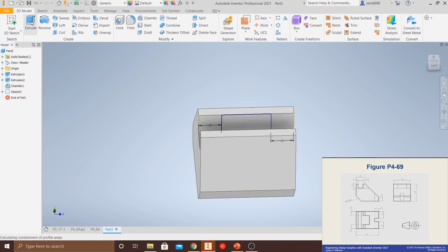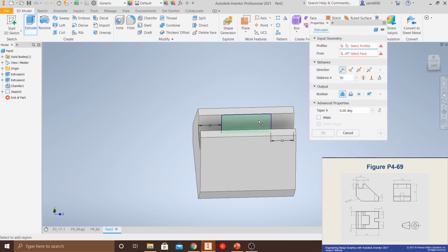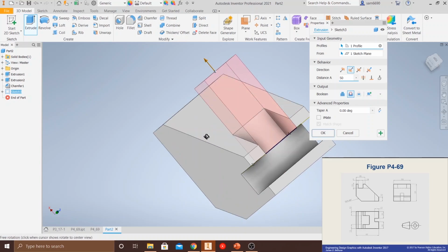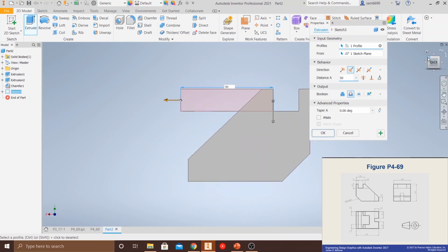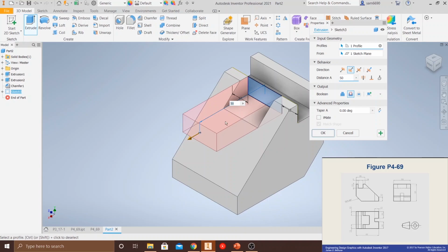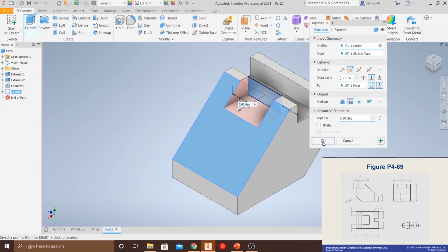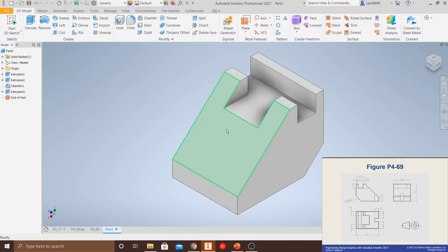And we're going to do Extrude. Click this Extrude button, click on the sketch, and we're going to do a cut. And you can see that it cuts straight through. You don't even need a dimension. You don't even need to know how deep it has to be. It's just going to cut straight through there. You could leave it like this, it cuts, but we're going to go 2, and let's click this face, click OK, and look at that. Now we've got this top cut right here. This top cut is good.